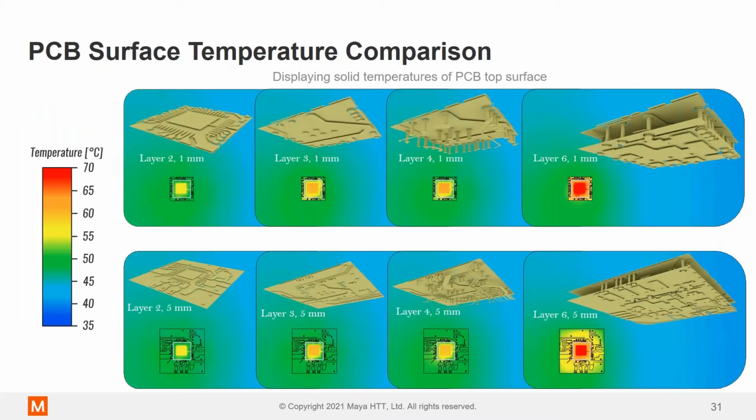Okay, so here's a quick comparison showing different thermal territory sizes, inflation sizes and depths. You can see there is quite a variation in temperature here, but what we found in our internal studies is that it's important to get the depth. You get the most accurate results when you model the depth in full, all the layers of the PCB going through to the bottom surface. And the inflation size isn't as important. So if we go to the next slide,